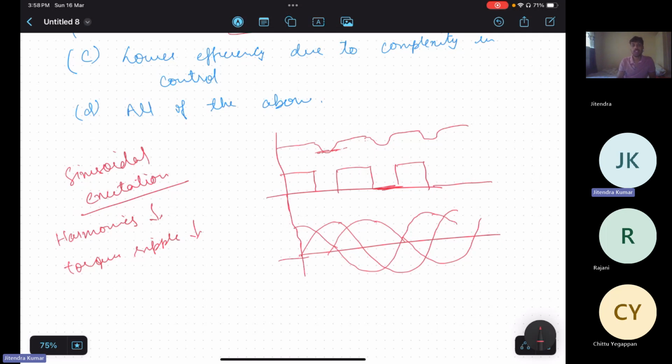Now, if you see the structure of the core, rotor, stator, permanent magnet, it will look alike. Both of the motors will be identical to each other. Only the slot-pole combination may change, which will again depend on how you have designed. You could also keep both of them the same.